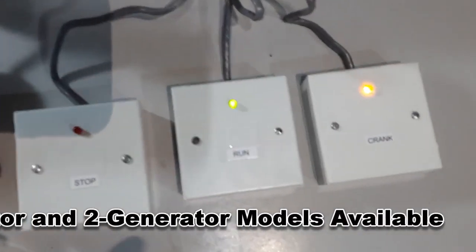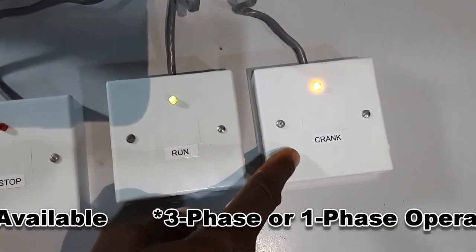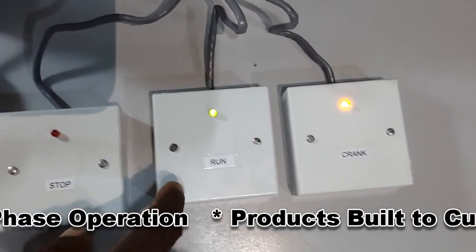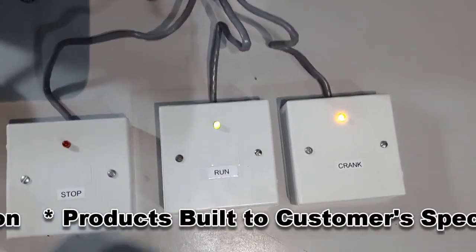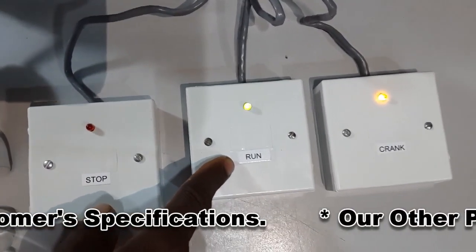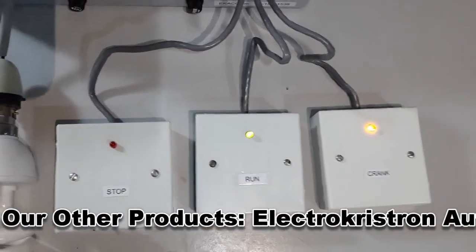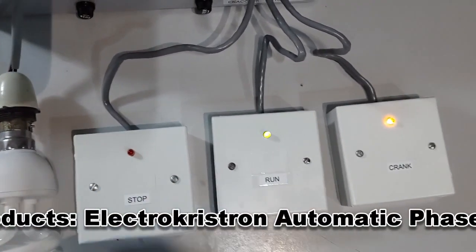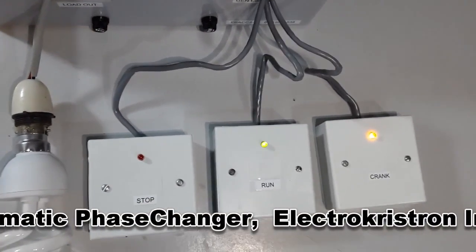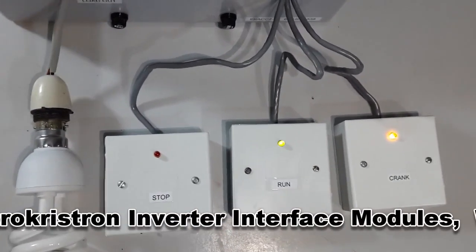Okay, now the first one says crank generator. That is, to roll the engine, to kick start the engine. And then of course there is another command which is run. Run is the one that powers the fuel system, so that the fuel valves can be opened for fuel to supply into the generator ignition system.